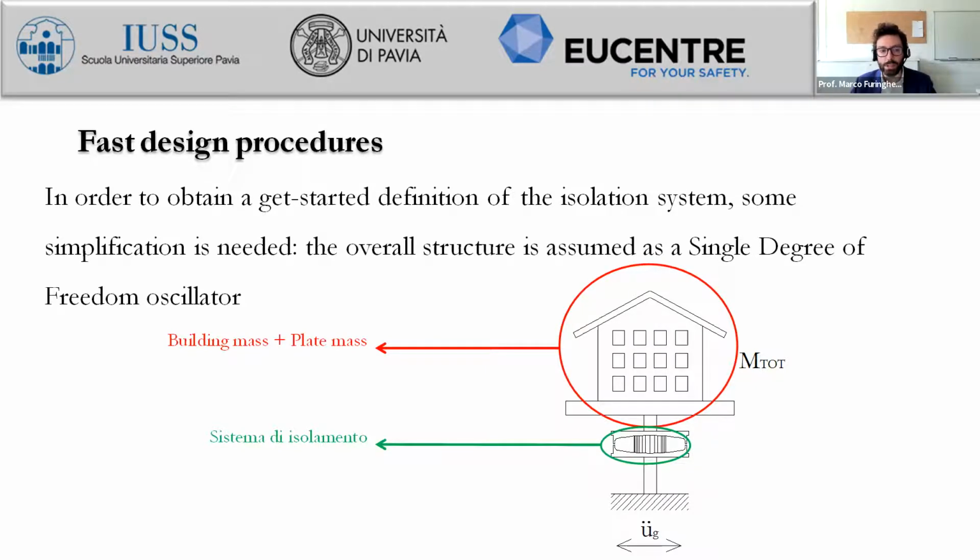We discussed the possible hypothesis of neglecting the mass of the reinforced concrete plate, and so we get a series of two springs, and we were able to compute the equivalent spring of this series.